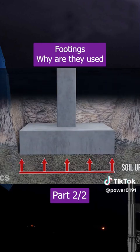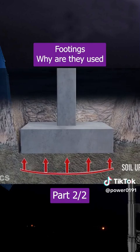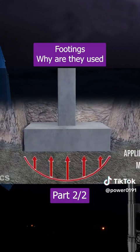This type of pad or isolated footing is employed to support lightweight houses that rest on soil with medium strength. This design can be further optimized economically. If you observe the pressure applied from the soil on this area, it is uniform. However, applied bending moment increases as we come to the center zone of the footing.